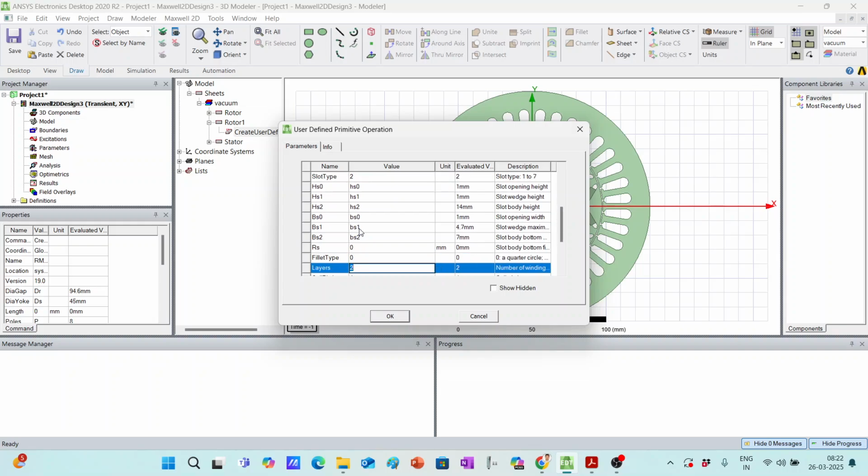Yes, it is a double layer winding, 36 slot 8-pole distributed winding, so it would be a double layer one. Coil pitch 4. Okay, I'll tell you. First, make this end extension and span extension 0. It is required for the 3D model, for end winding, so currently make it 0. Seg angle is 0, limb region 0.